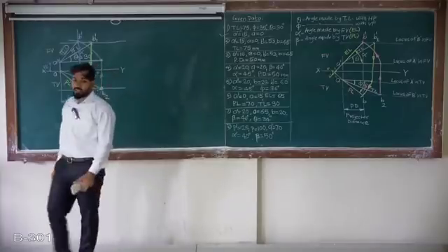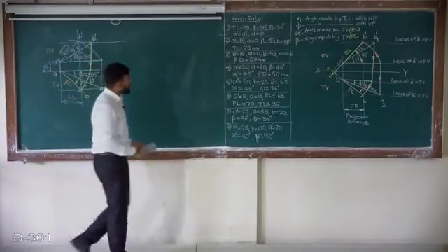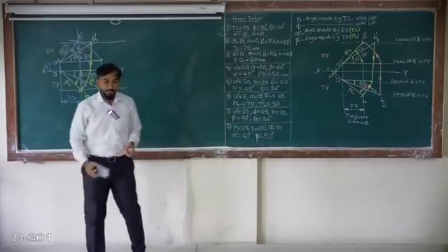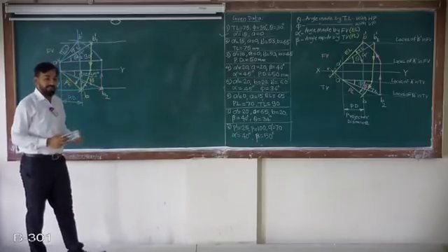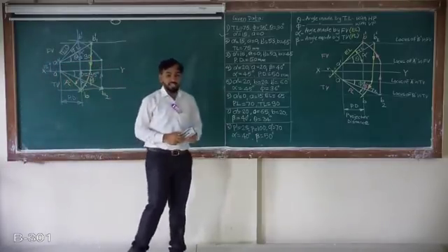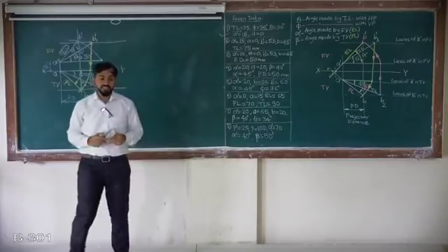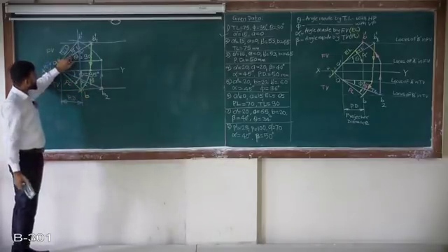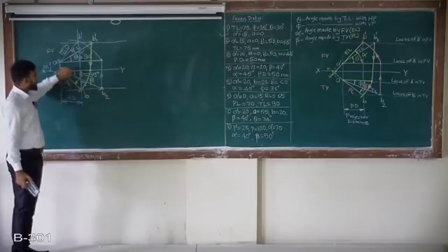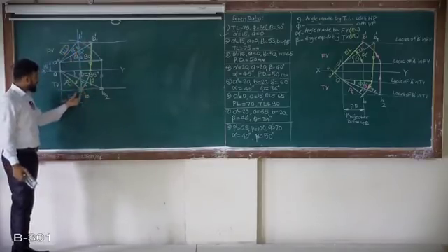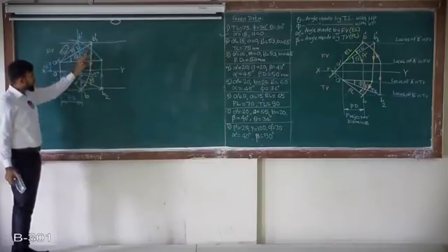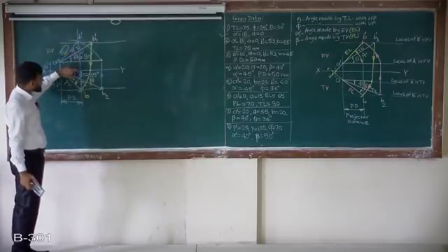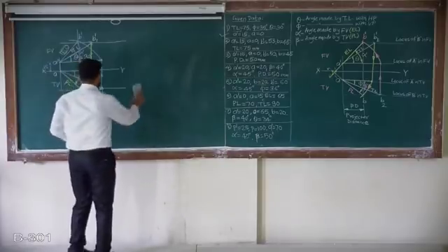So now every problem you will try to relate with the first basic thing of the first problem: TL, theta, phi. So got it? That's very simple. When I was knowing 5 parameters as TL, theta, phi, A dash and A, first I need to plot the 5 parameters A dash and A. I have marked here the true length and corresponding angles. I got the points B1 dash and B2. Then I got points B and B dash by projecting the true length points and rotating on the corresponding locus. And the corresponding angles are alpha and beta. So now we'll see question number 2.